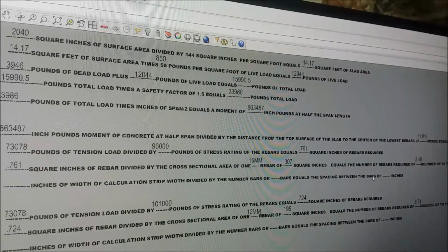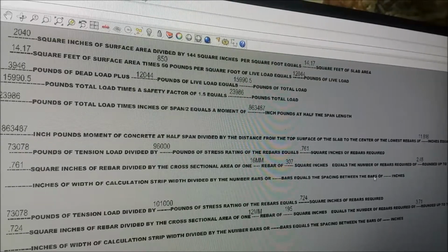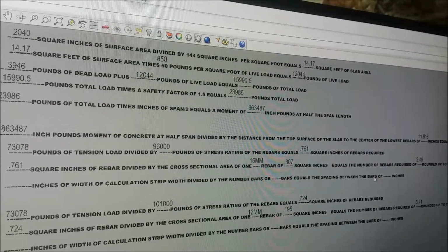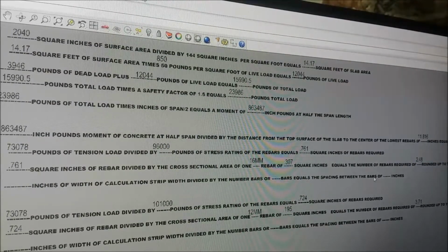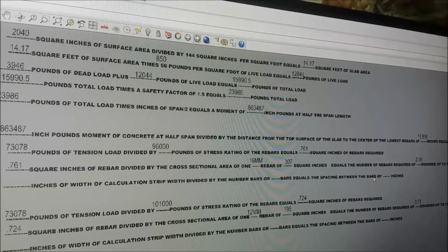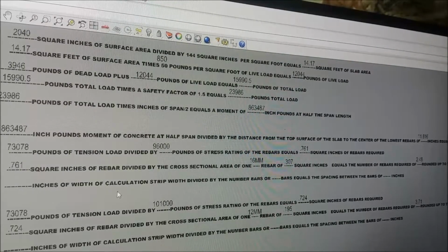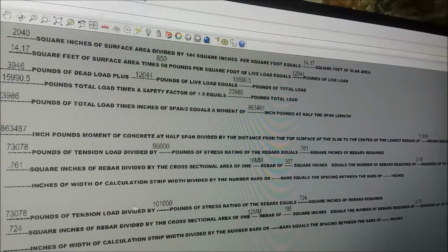You could put it in there and it'd tell you probably a best spacing to use, but it would depend on how it fit across the bottom of the beam. You're going to put them in that space, one near each end, and the rest of them pretty much evenly spaced across the middle. So we did this calculation for a 16 millimeter. We're going to do the same calculation for a 12 millimeter.